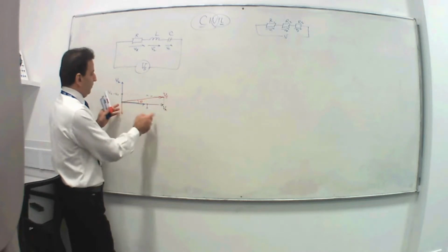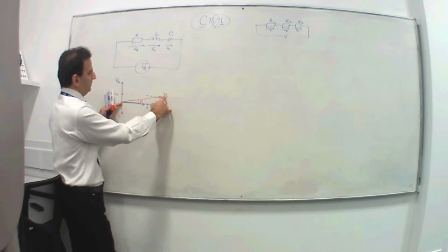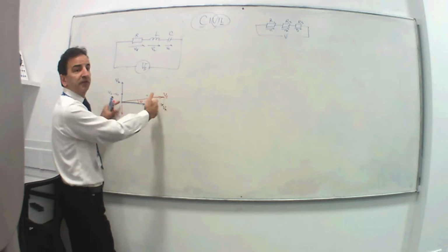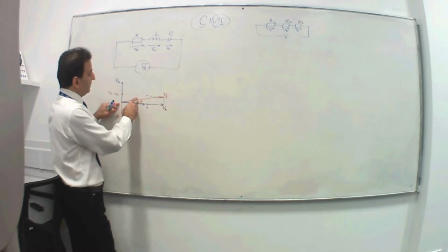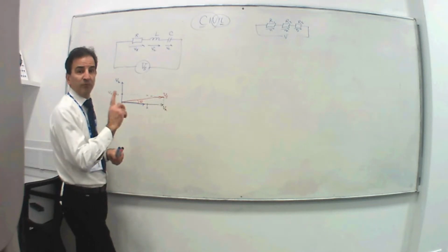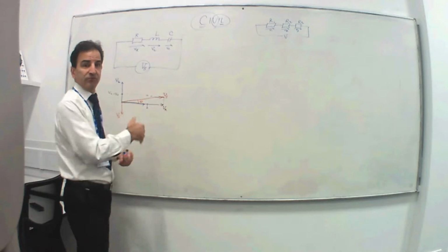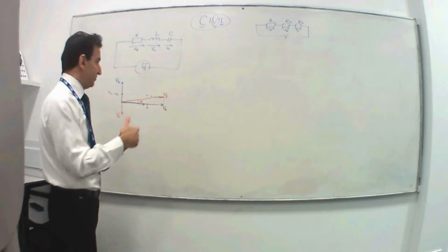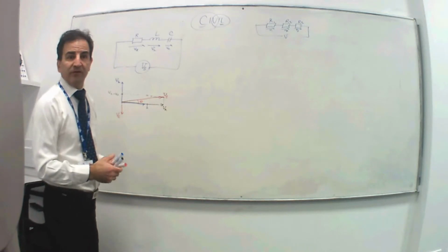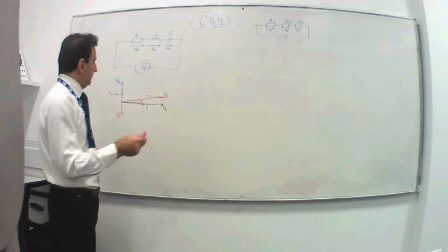And then when you draw this, measure that with a ruler, times it by your scale, you find the VS, and then measure that phase angle with a protractor. And that's one method, the first method, actually drawing everything to scale, which is not what we want to do. This is a little bit lower level, level 2 or 3, that do that.